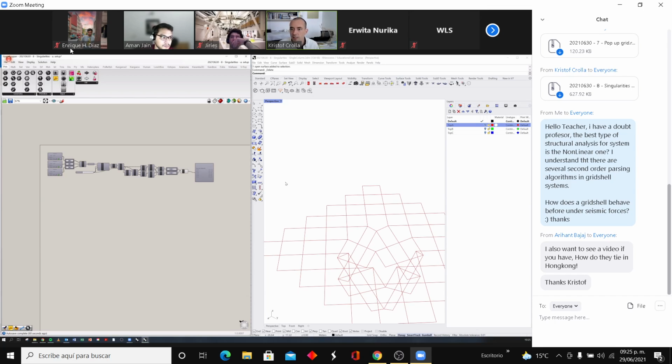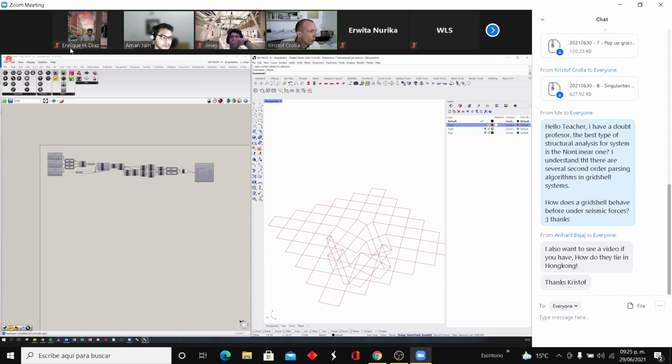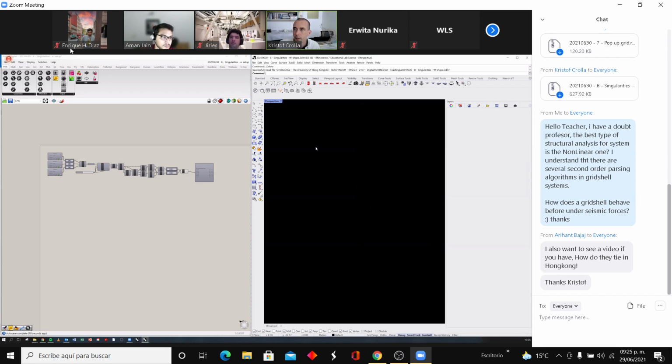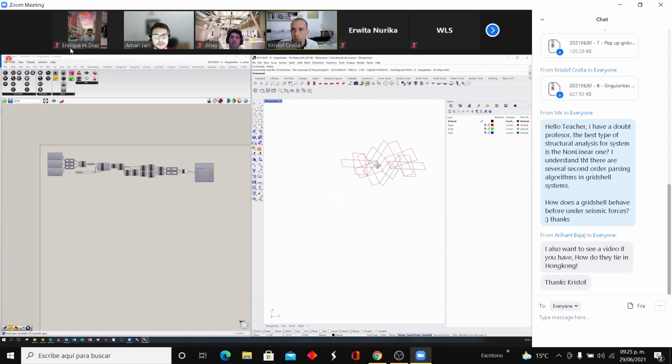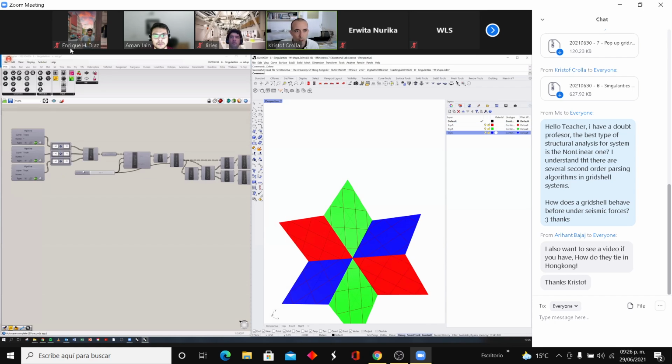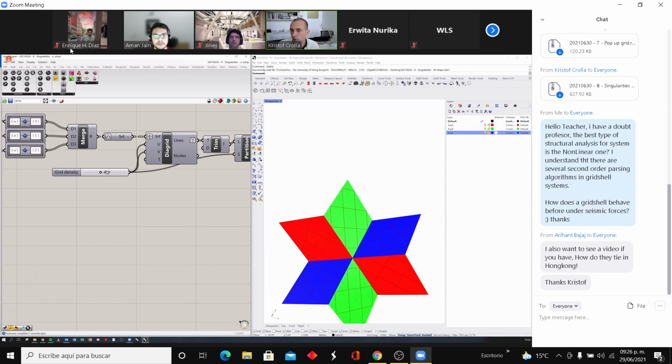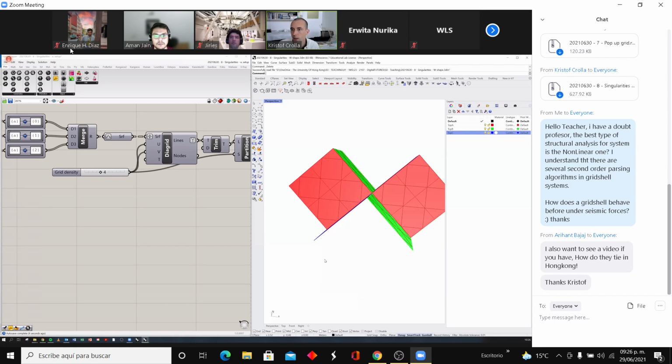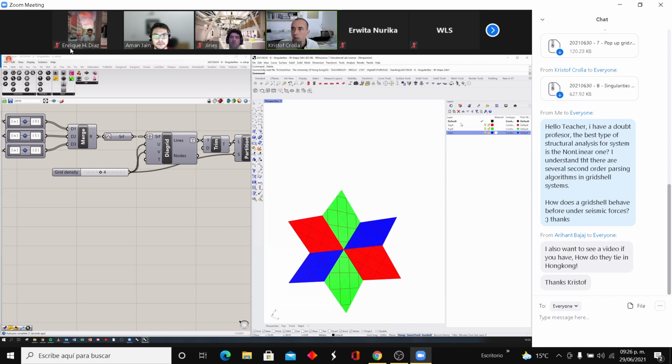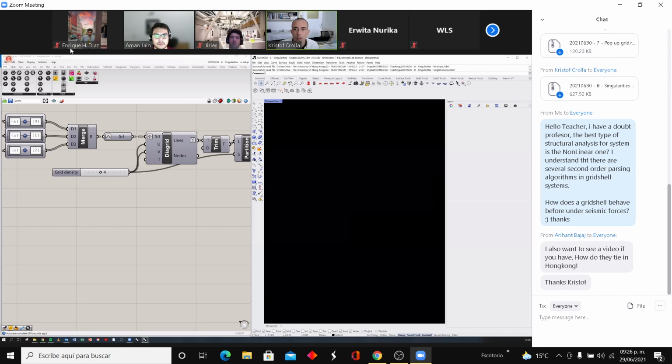Pretty straightforward. So the nice thing about this is whichever topology that you'd be working with, and let me just open up a different Rhino file here. So I'm opening the W shape here. Yeah, so for this one, this kind of works as well. So it's a different input setup, and you see now it's creating a hexagon in the middle, and you can increase the resolution to as high as you want to have. So it's kind of a flexible script that we have, but we need to always work with these types of topologies. Okay, let me go back to my column and let's go to the second script.